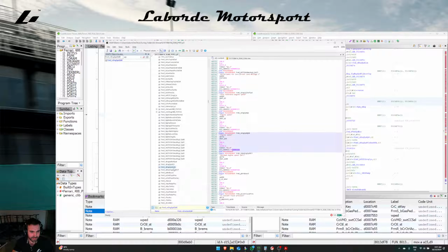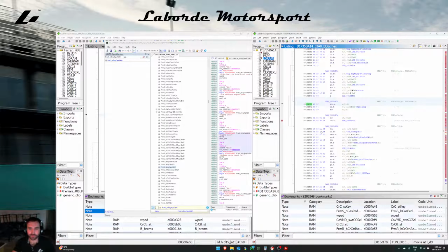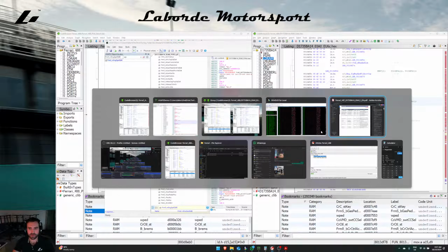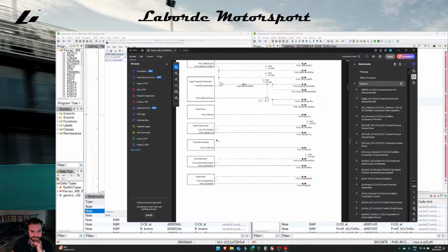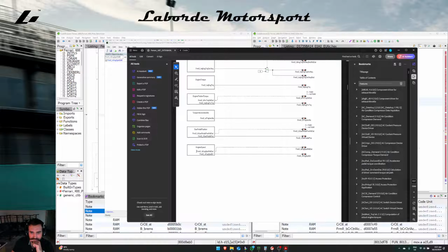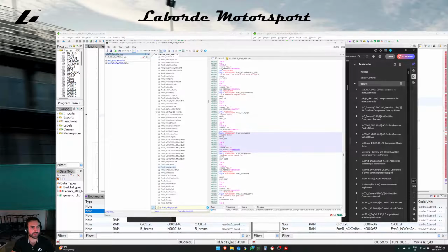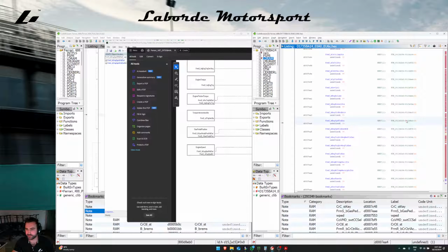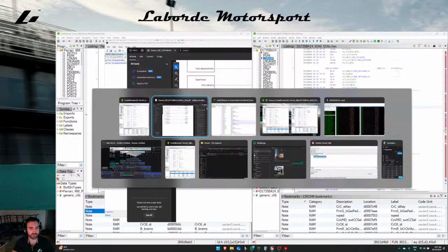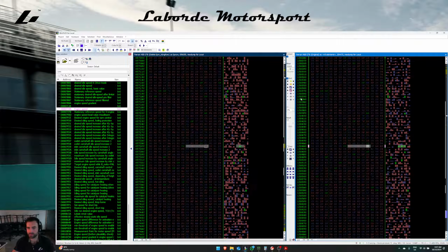So these are one of the things that we're going to have to go through and try and find. Idle reference speed. Maybe we can find an example of where this variable might be used elsewhere, or some other variables that might give us what we're after. Gas pedal position. So we've got here FRM SB engine speed valid. I'm guessing that's telling us whether or not the engine speed we're referencing is indeed valid. Let's see if we go to that address here and try and find some similarities between the two files. Let's have a look. Nope, nothing there.